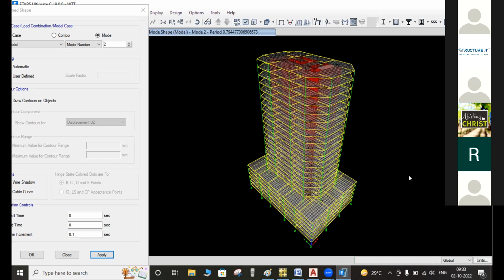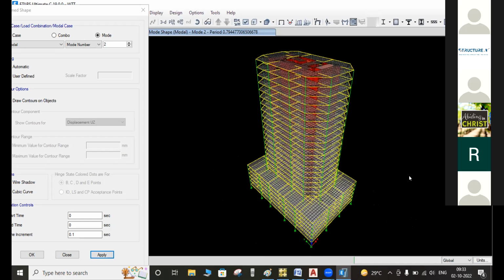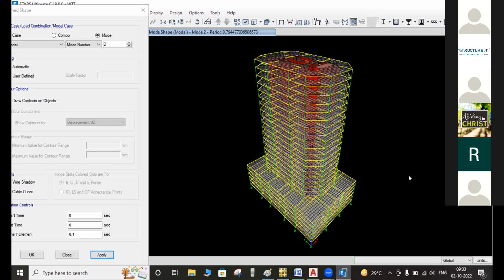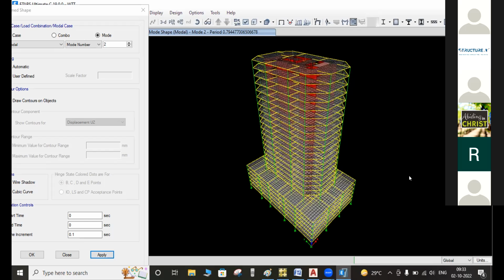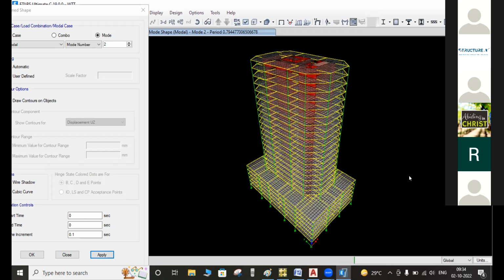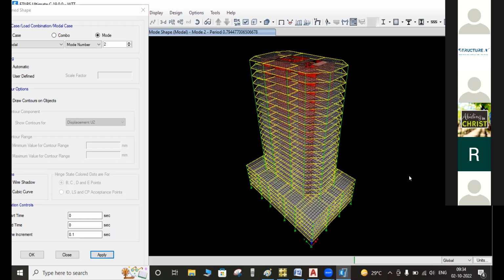Okay, so what is the allowed percentage of rotation in the second mode? Basically, sir, when we select the third mode, mode 1 and mode 2 are modified in such a way that their values become less than 10%. The third mode, as per judgmental assumption, has a lump sum of 40 to 60% torsion. Okay, so kindly can you share that table?